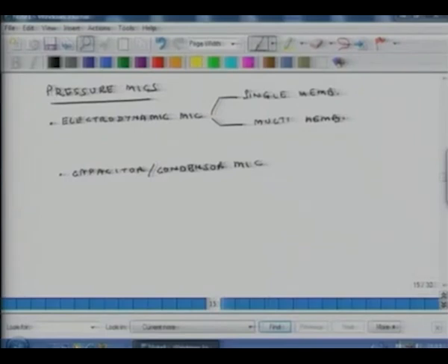Here we are actually measuring the charge on the capacitor. Now, within this, there are two types: polarizing and non-polarizing, which others also call electret. In polarizing, as we have seen in the earlier part of today's lecture, you have to put an external battery to provide an initial polarizing charge across the two capacitive plates. That makes things very expensive. The polarizing type of mics are very accurate, and they also have a very flat frequency response, because when we did a very basic analysis, we saw that the relationship between pressure and omega is a flat line, right?